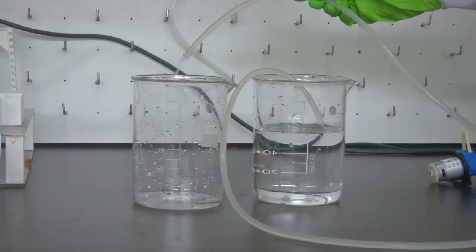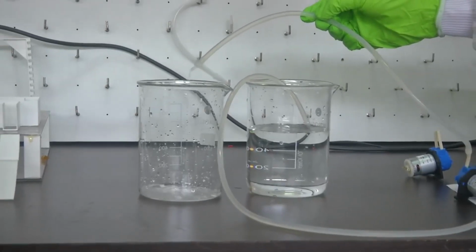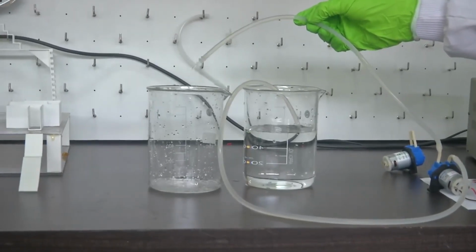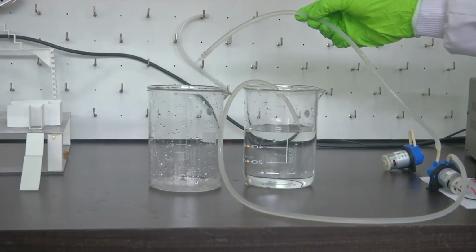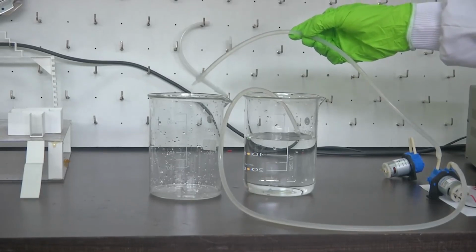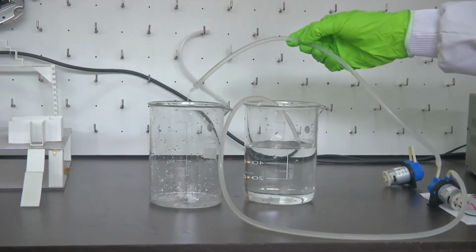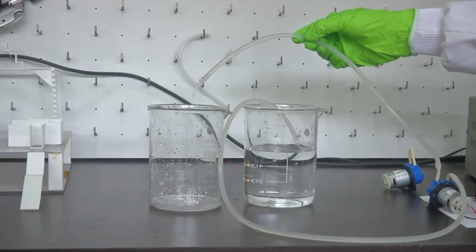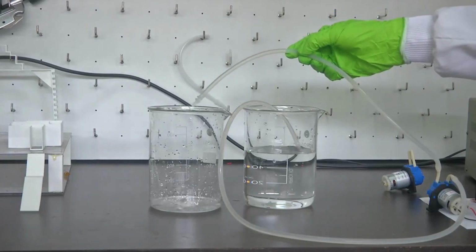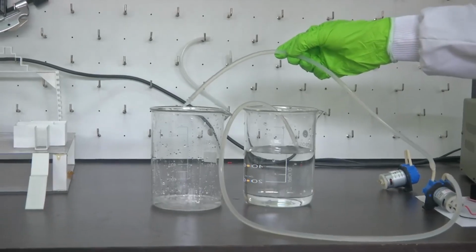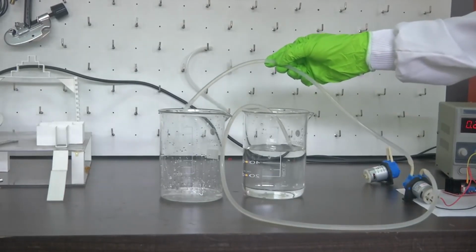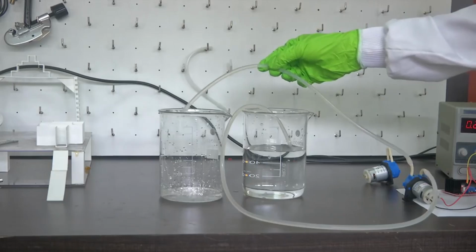You can see that water is not falling continuously. It's falling at discrete intervals. This is because, as you must remember, a peristaltic pump is not continuously pushing water. It will push water in the tube for a while and then the roller will lose contact. It will come again, so there is a small gap, and that's why it's pulsating and not continuous. I hope you understood this. This is one of the pumps that we use very commonly, mainly because it is very accurate and consistent.